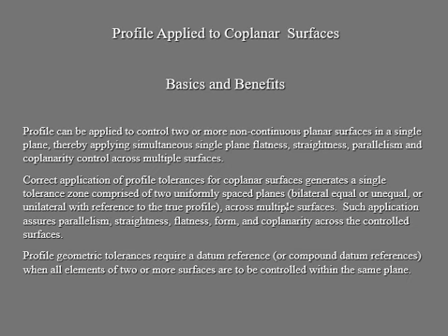By doing that, you can verify your parallelism, straightness, flatness, form, and coplanarity across the controlled surfaces. Surfaces are being controlled because don't you ever forget that you are manufacturing them. So if you don't control with the tolerance or value, your manufacturing is going to go crazy. Because you are producing billions and billions of parts of the same design, even though you're using the same machine, it will get exhausted over time making the same thing.